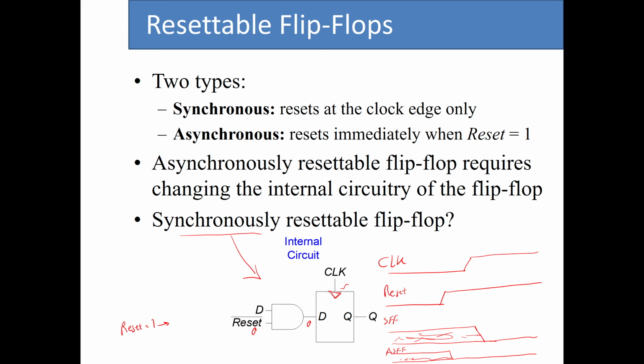As for the implementation, the synchronous resettable flip-flop is much easier to design, and a lot of the time it may be even enough to have it being resettable synchronously. But in some special cases, we require an asynchronous resettable flip-flop, which requires that we make some changes in the internal circuitry of the flip-flop.